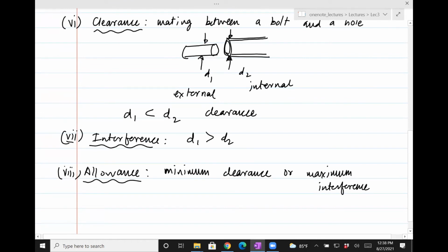It is so called because when you are talking about a shaft going inside a hole, you don't want too much gap. So you want to have the minimum clearance, but it should still go. The interference in this case is maximum because you want to find the maximum limit at which they can get that interference. Okay, so here is a problem on clearance.